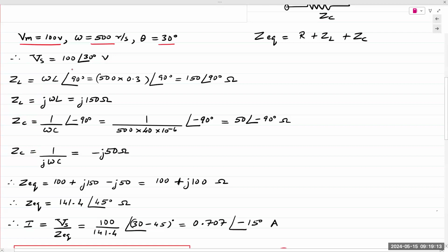The question being asked is about the plus 90 and minus 90. That comes from the fact that the current for an inductor lags the voltage. ELI the ICE man: voltage is ahead of current in an inductor. Z itself is simply V over I. Voltage is ahead by 90 degrees. So when you have two phase angles being divided, for an inductor, it's always plus 90. For a capacitor, it's always minus 90.